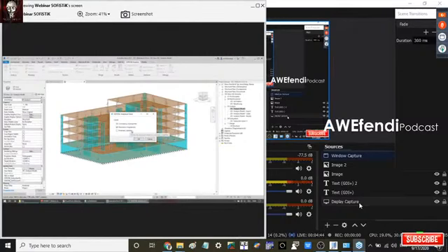And what is also new for version 2021 is that we also check for kinematic stability. This means if a member is not connected or is not properly supported, you will encounter kinematic instabilities during analysis. And in order to avoid these issues, you can check that before and search for those situations.